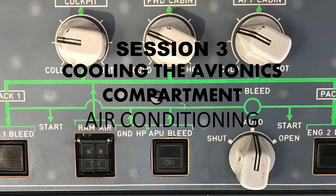So that gives you a good idea of the components involved with the ventilation system for the avionics equipment, and the three different circuits that we can have depending on conditions related to temperature and pressure, whether the aircraft is on the ground or in flight, all those different variables coming together. And of course you have the computer, the brains of the operation, to ensure that's all happening.